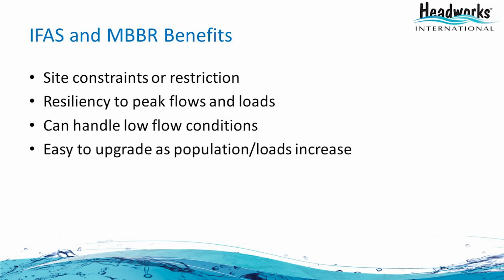Again, the benefit of these biofilm technologies is if you have site constraints, you don't have any room to expand, you can easily put in an MBBR or IFAS plant within the existing tanks. And the next advantage is that it's resilient to highly variable flows and loads. The biofilm automatically shrinks, grows, and adjusts to the new load conditions. Then it can also handle low flow conditions.